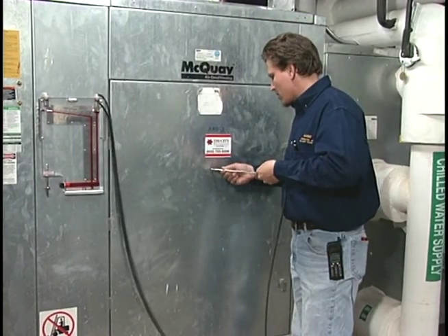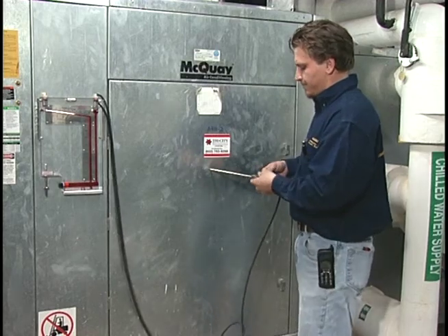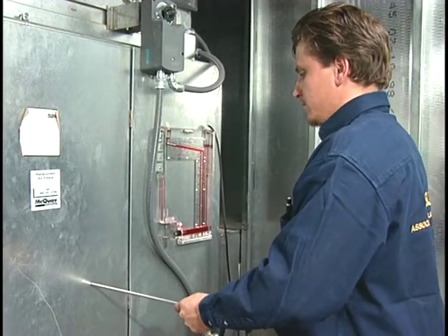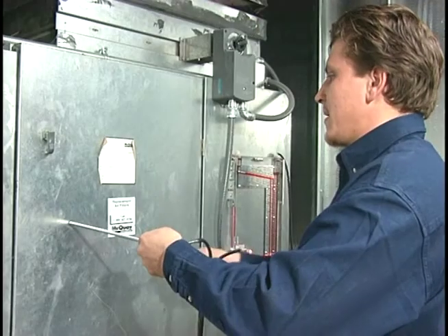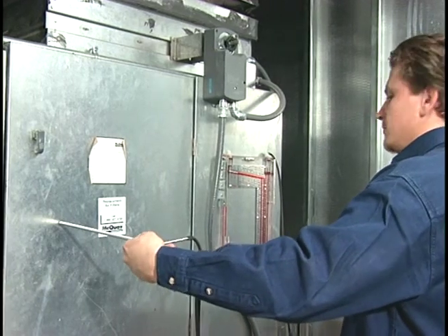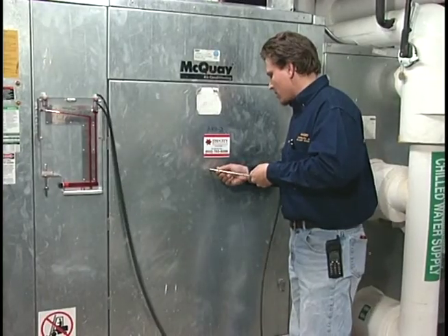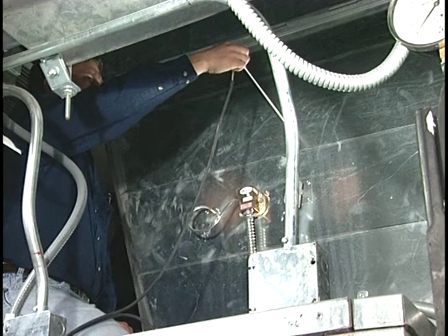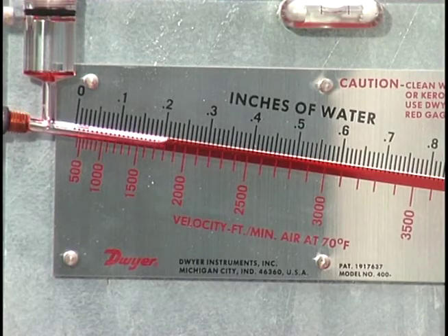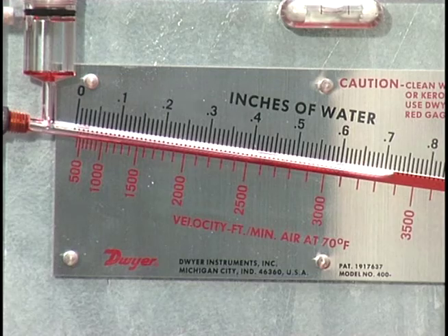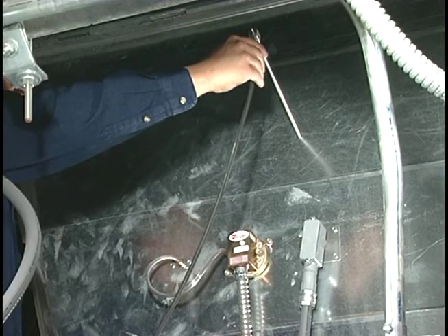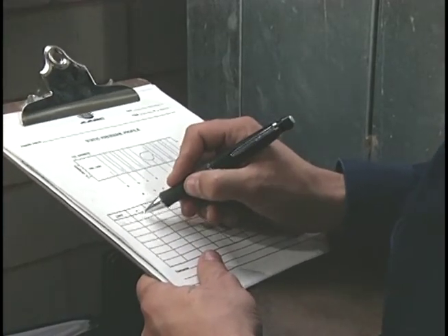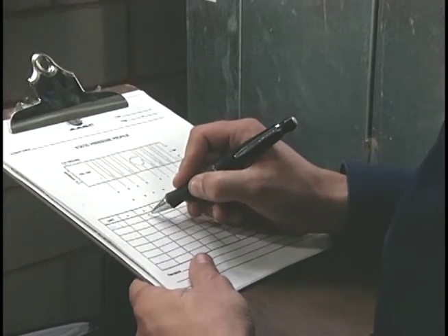For this air handling unit, the technician takes static pressure readings across the filters and coils and readings entering and leaving the fan. Point A is in the mixed air plenum before the filters. Point B is leaving the filters and entering the cooling coil. Point C is leaving the cooling coil and entering the fan. Point D is leaving the fan. A negative static pressure reading at C and a positive static pressure reading at D will give the fan's total static pressure, or TSP. The TAB technician records the actual static pressures on the appropriate data sheets and compares them with specified data.